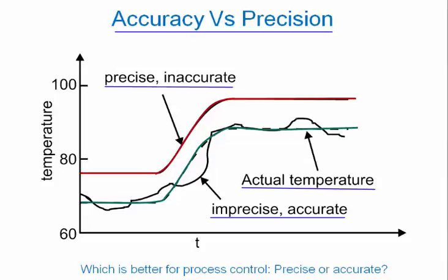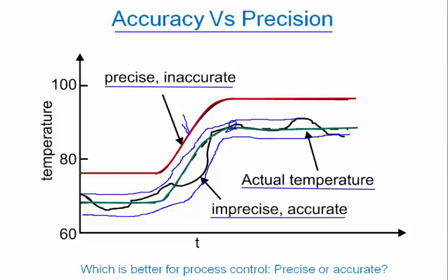randomness is creating what we call an envelope. So there's an envelope there which is really expressing the accuracy of the whole thing. If I draw that envelope, then that contains all the deviation that we see. But here we've got something that's precise, it's correct, but it's inaccurate because there is an offset here. This whole measurement is biased upwards on the temperature scale.